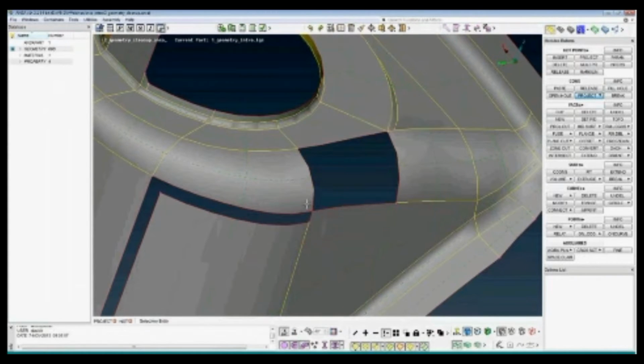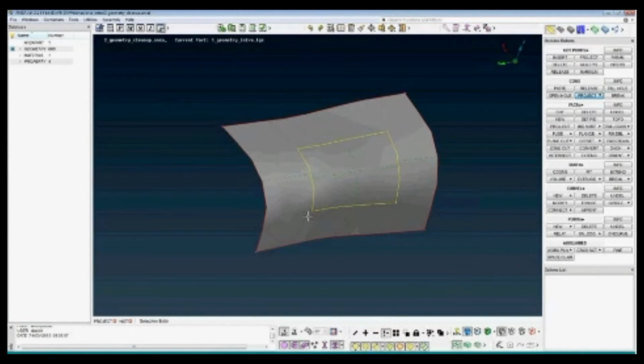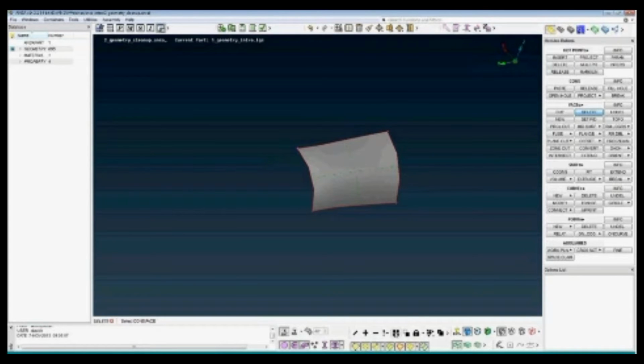And now take a look at the large face. We now have cut the face. We have yellow boundaries. It means that the 2 faces are connected. You can delete the outer face. If I pick on the boundary, I get the selection as we saw before, or I can pick directly on the crosshatch. Then the face is deleted with no question.